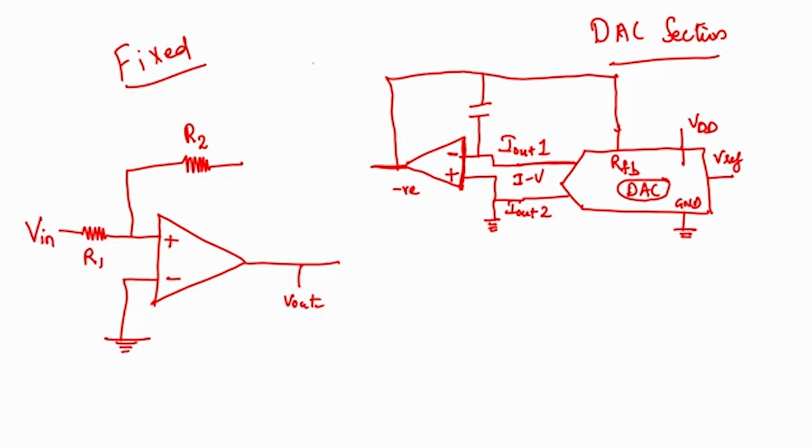So this DAC portion is ready, that portion is ready. Now we have the fractional. So what else is missing here? We missed a very important thing here, correct. We missed the digital input, no. So digital input will be there, D11 to D0, which will control the output that you finally get here, correct.